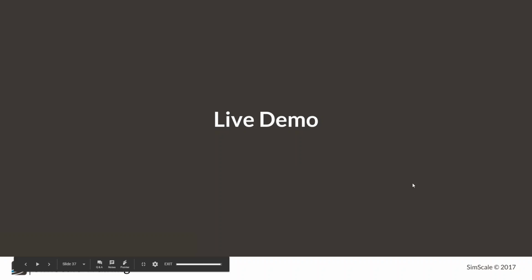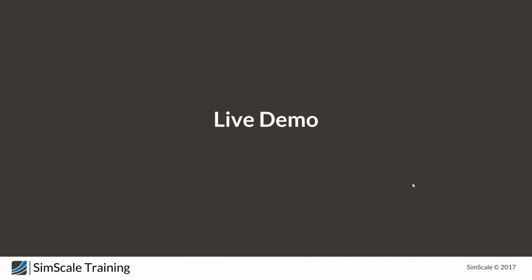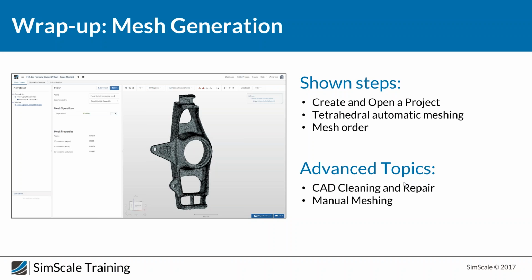Right, now I'm back, sorry. So the first step is creating a mesh, and there you just need to create a new project, choose tet-dominant automatic meshing. We choose a mesh of first order since we don't expect to have large deformations, and start the meshing project.